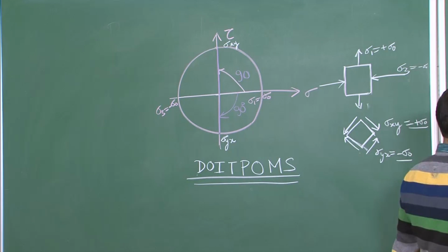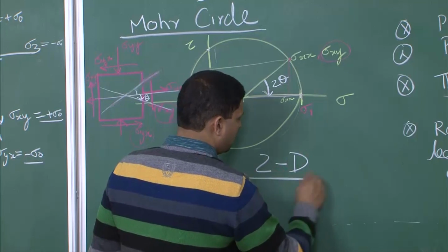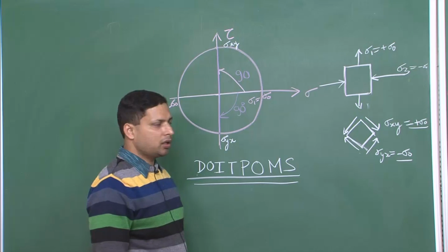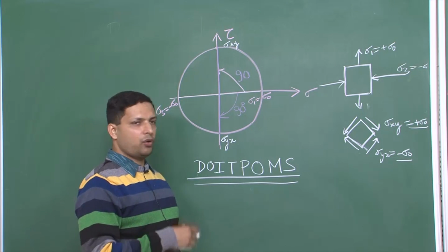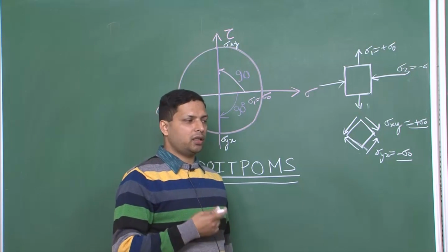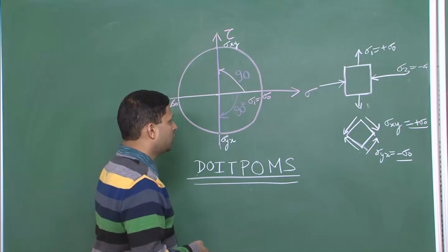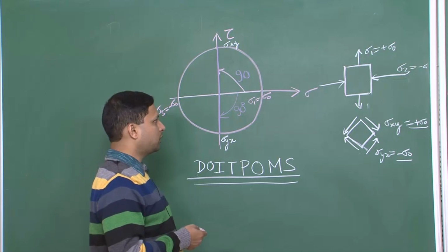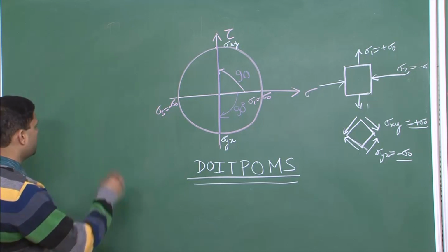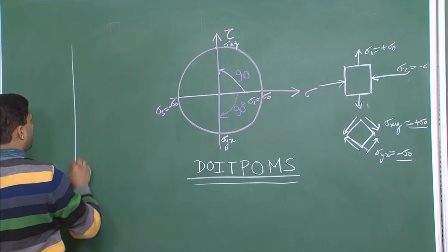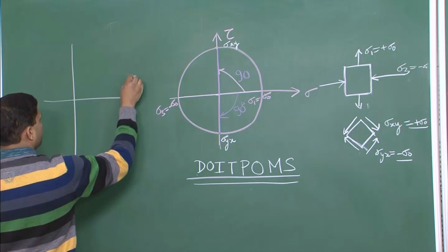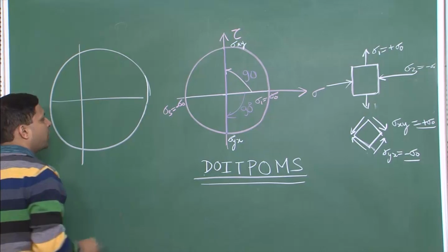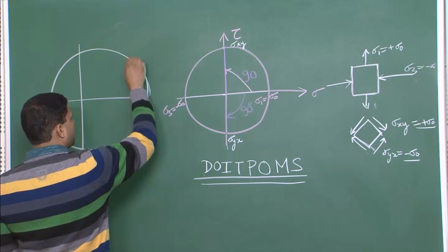Now, we have looked at a 2-dimensional case so far, remember. So, we had no stresses acting in the third direction. How would the Mohr circle look when the third direction also has some stresses? That is not very difficult to judge from here actually. It is just a simplified or extended version of this. If you have a 3-dimensional stress condition, it is not represented by a sphere, but still by circles, but now instead of one circle you will have 3 circles.